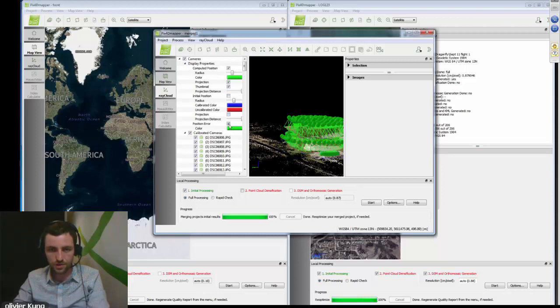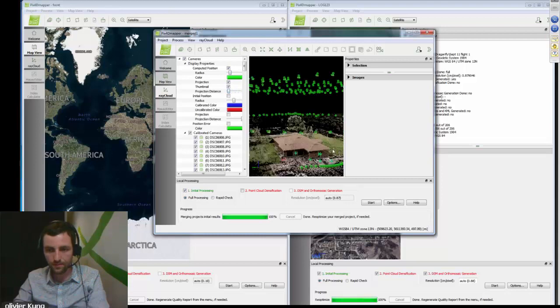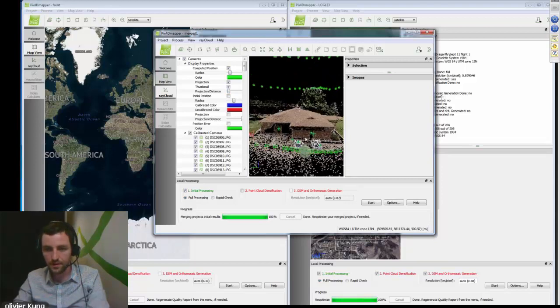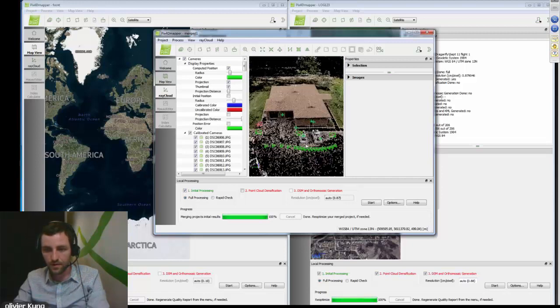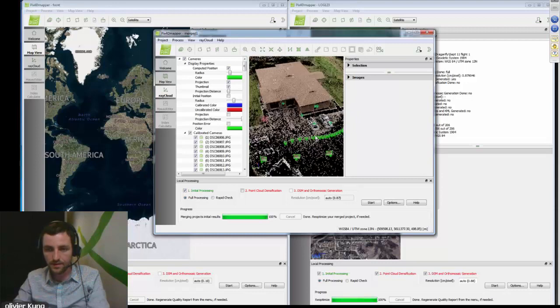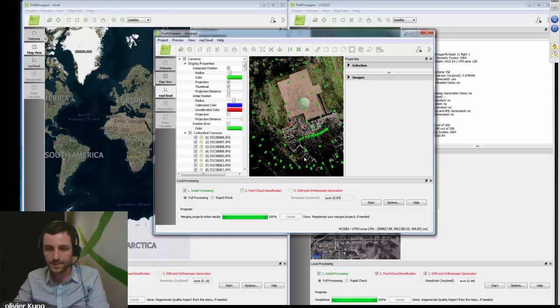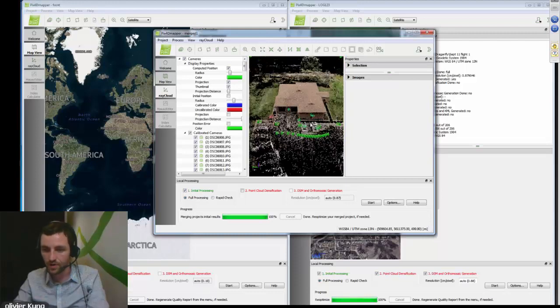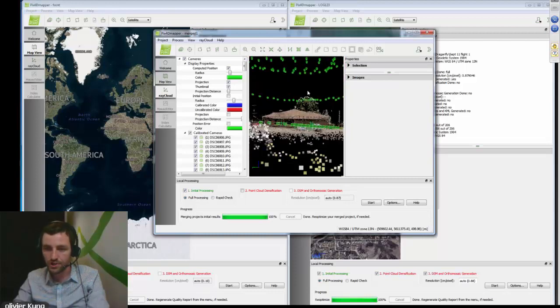So let's change a bit the visual properties to have a clearer view. Okay, and this is what just happened there. You have the ground datasets taken with the Canon camera and the aerial datasets taken both Nadir and Oblique with the Sony camera merged in the same project.